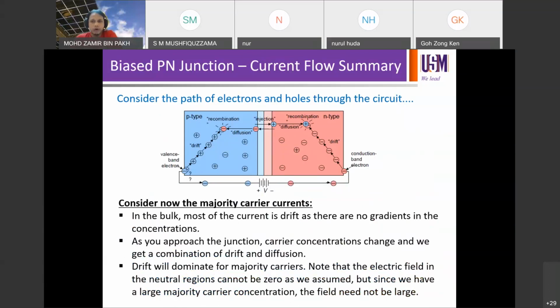Well, you can also argue this because we learned last time that the electric field is the strongest in the diffusion region, but it's very, very weak in the quasi-neutral region, but it's not zero, right? So the moment it's not zero, you're going to have the drift component as well. Because of the electric field, as long as you have electric field, you're going to have drift. It doesn't matter what the amount is. The higher the electric field, the higher the drift.